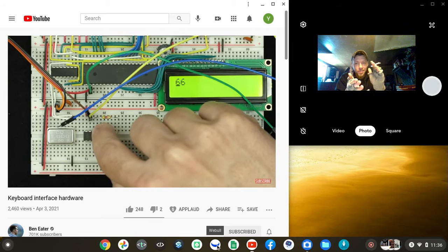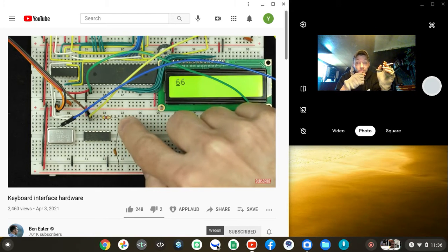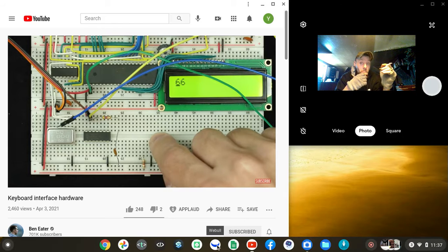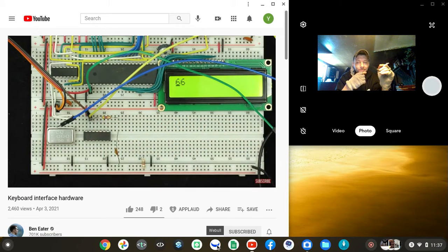And then when the output here drops back to 0, this point here won't immediately go to 0. It'll stay at 5 volts, and then slowly discharge as the capacitor discharges, essentially through the resistor into that pin that's now at 0 volts.